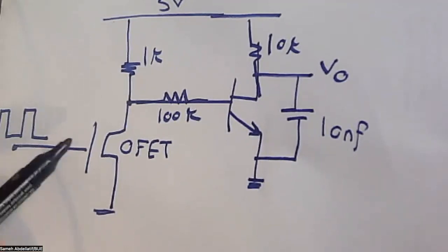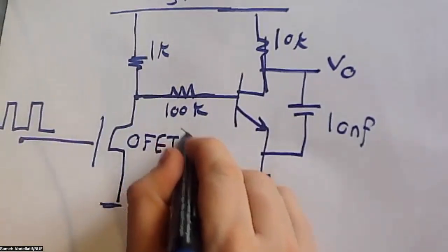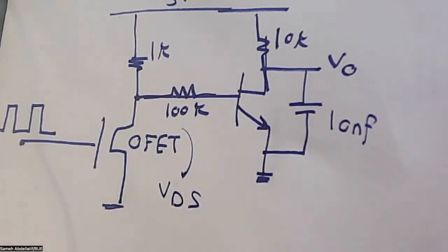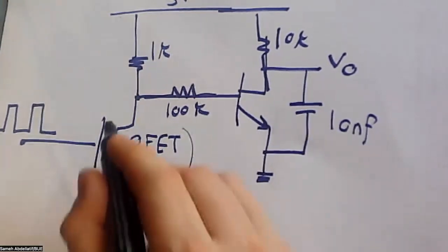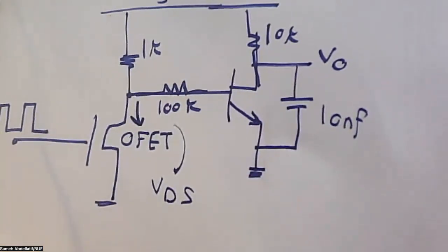Now, let's assume that this OFET is turned on, and this OFET structure works to measure lactate. And as we already considered, the voltage here, the VDS, will be kept constant during the experiment. And what will change is simply the current flowing here, which is the ID.